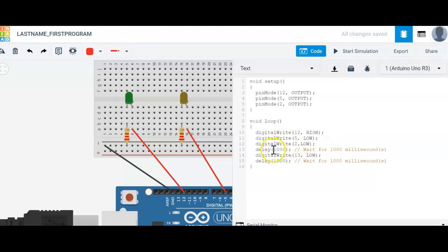So remember, the unit is not seconds, it's milliseconds. So this is delaying for 1000 milliseconds, or 1 second. So let's go ahead and change that to 5 so that we can turn this green light on for 5 seconds. And that'll be our first kind of section there. So we can put spaces in. Any space is just ignored by the Arduino when it's actually reading this code.